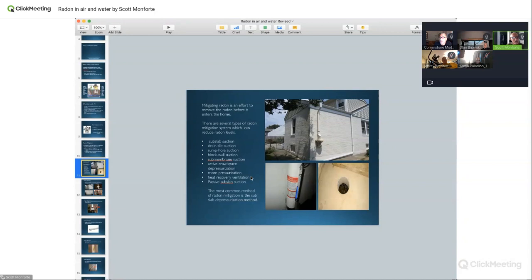The reason they want it on the outside and they want it in the attic or the garage is if there was damage to the pipe, it wouldn't blow the radon through the house. And that's really what it's all about. We tell everybody every 2 years, test your home. Obviously, if it's not working right, the radon levels are going to be high. Most people, after a mitigation is done, you give them a device to test, because we're not supposed to test what we mitigate, but we certainly can give them a device, because I want to know, did my system do the job? And I want to know immediately so we can go back and fix it, make repairs, or do whatever we have to do.